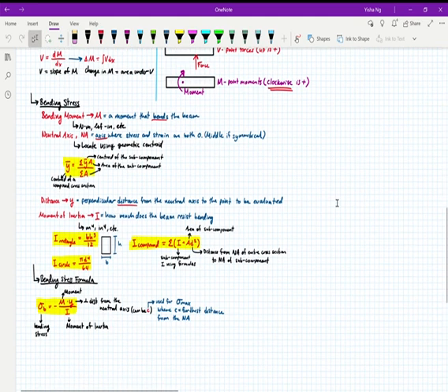Okay, bending stress is the other big thing that we need to calculate. A couple variables are bending moment, which is M, the moment that's bending the beam. Your neutral axis is the axis where stress and strain are both 0. If you have something that's symmetrical, it's always going to be down the middle, so like a rectangle, down the middle of the rectangle, or a circle. Otherwise, you locate the neutral axis using the geometric centroid.